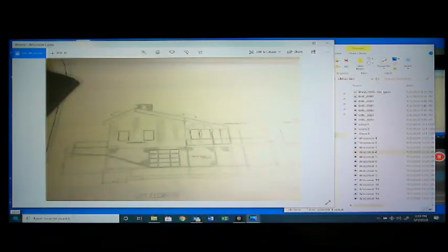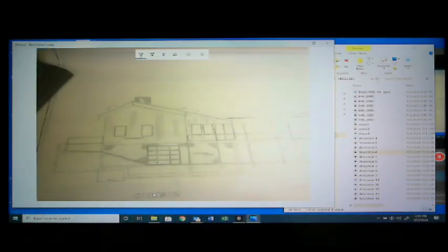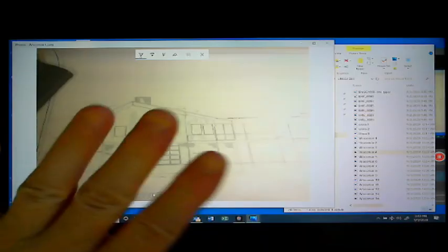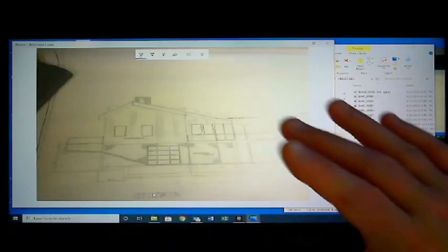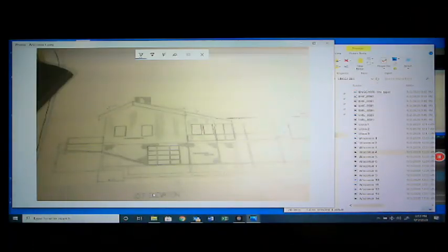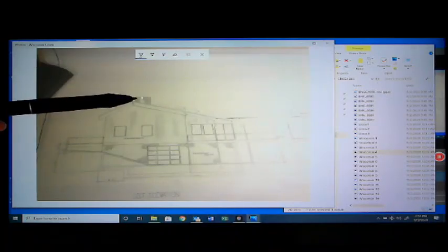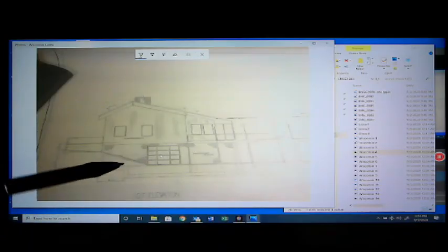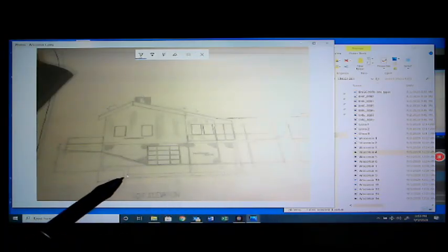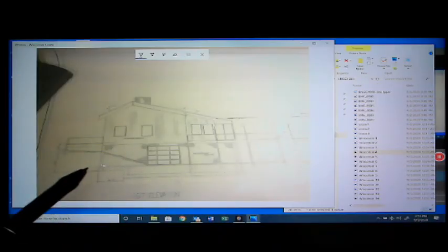And this is the left side of the house. In architecture, rather than call it the side, they call it the elevation. Basically this is just a flat view looking at what you would see from the house. There's no perspective, nothing's going off to a point in space, like two railroad lines that meet at some point. All right, so the fireplace is there, and here's the chimney on the far side. You can see the underneath-the-ground dotted lines. These are hidden lines in this case, is what these dotted lines mean, showing the foundation.